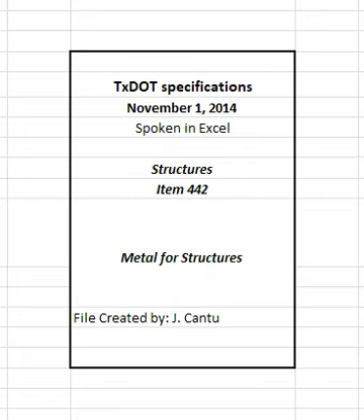3. Construction. 3.1 Fabrication, erection, and painting. Fabricate, weld, and erect structural metal in accordance with Item 441, steel structures, Item 447, structural bolting, Item 448, structural field welding, and the applicable AWS welding code. Paint in accordance with Item 446, field cleaning and painting steel. Aluminum or galvanized steel members do not require painting unless otherwise shown on the plans.